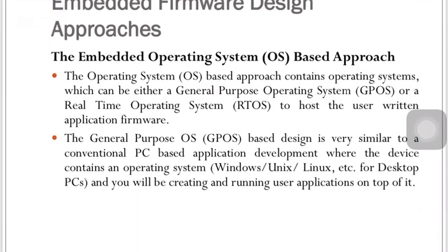Then the next approach is the embedded operating system, the operating system based approach. Where the embedded system tasks are very critical and the response time is required to be faster, or where we need scheduling or prioritizing of tasks, there we need operating systems. The operating system based approach contains an operating system, which can be either a general purpose operating system or a real time operating system.